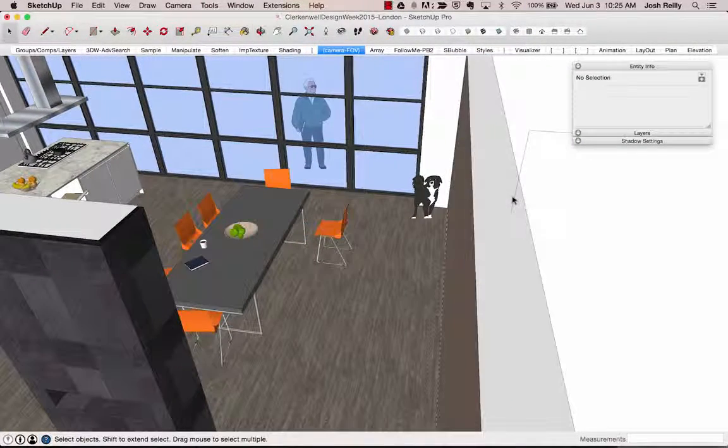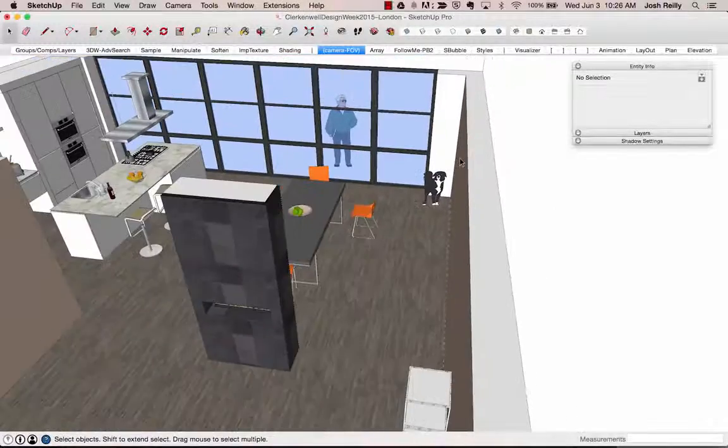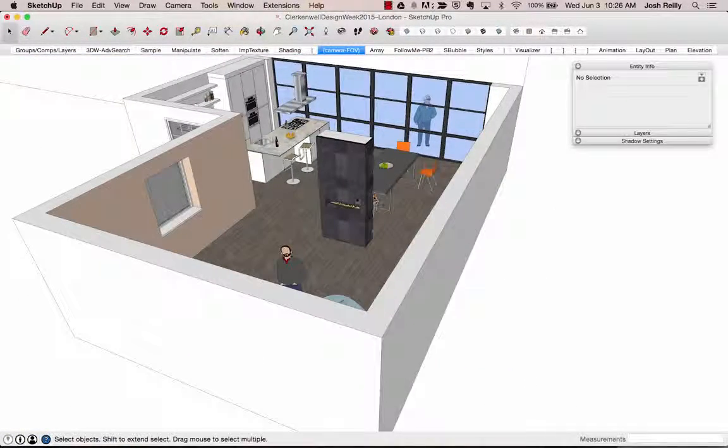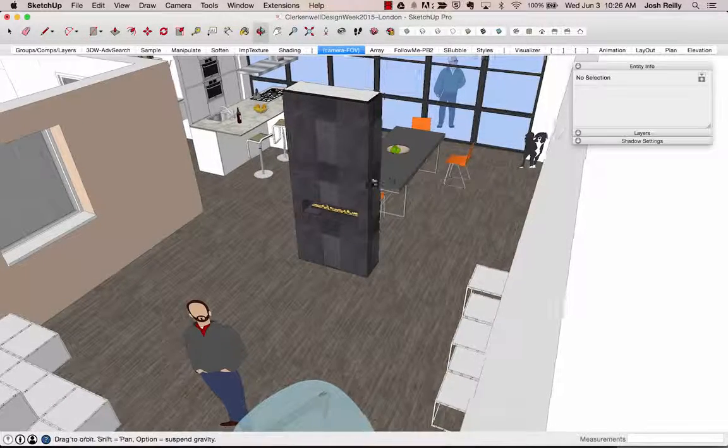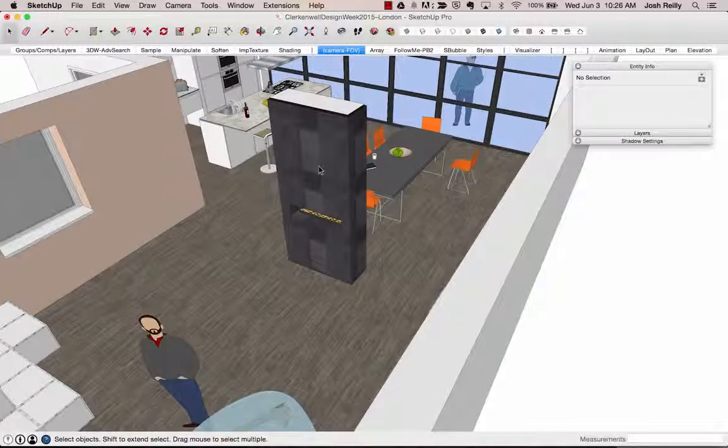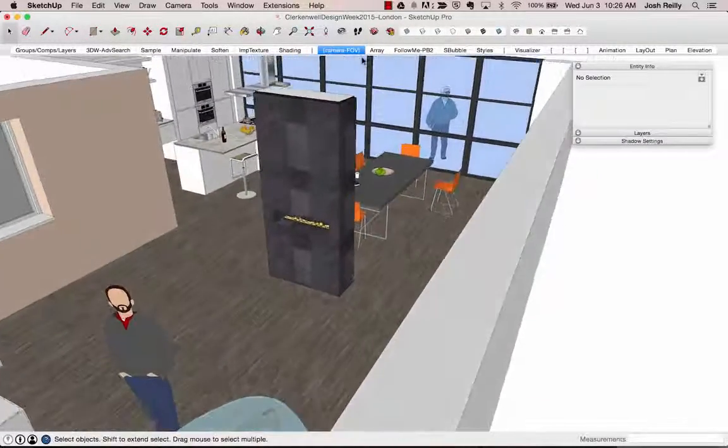So that's really important because you want to master navigation in SketchUp first. If you're really new to SketchUp, perhaps download a model from the 3D Warehouse and just practice navigating around it. That's really important. It helps you model more efficiently, and it's also, as I said, a nice way to show your model to somebody else when you're not fumbling around and navigating kind of rough. So let me get back into these tools here.